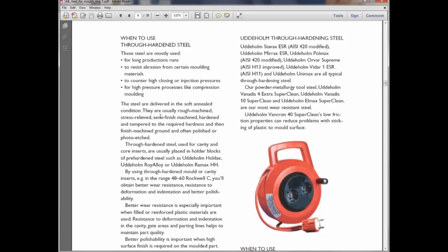So at that time we go for stress relieving after this rough machining. Otherwise the part can twist, or deform, maybe bend. So what we do is release these residual stresses. At that time we go for annealing or tempering.